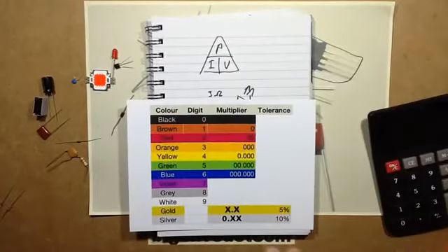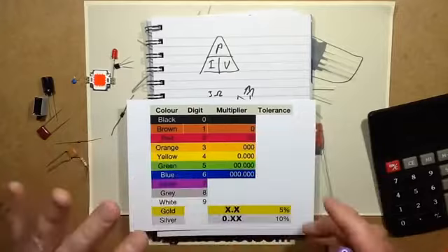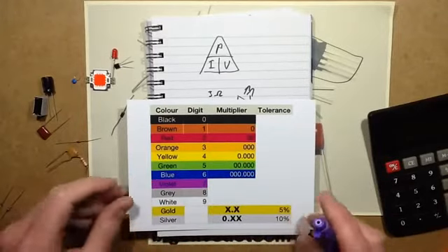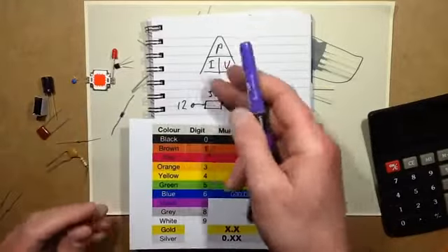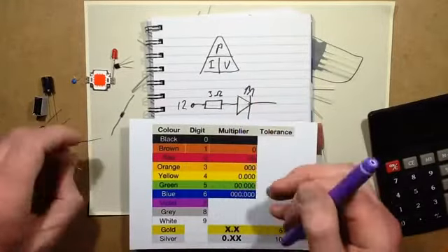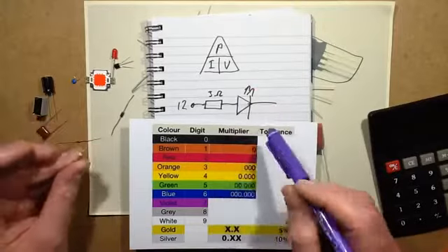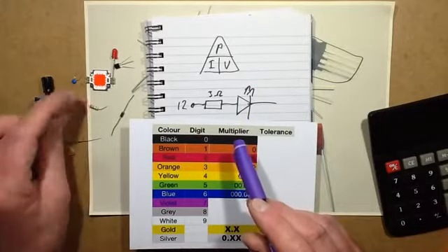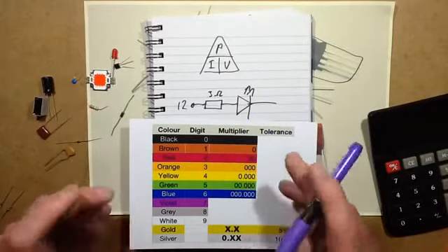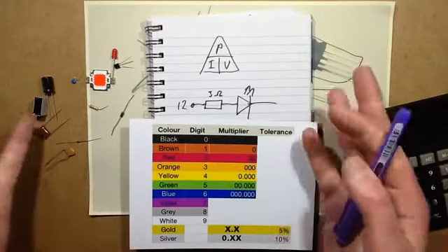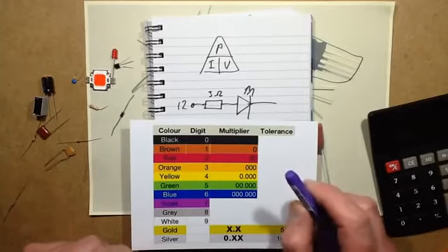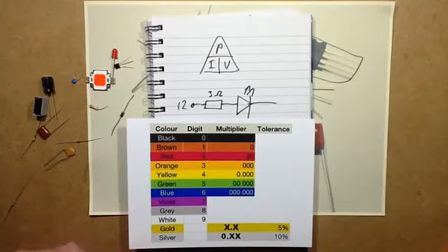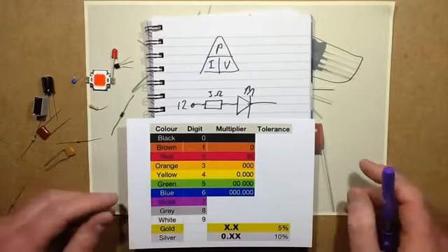That's just a summary. I'm not going to go into too much detail because it would get boring very, very quickly. But this is just the basics of what you need to know, how to work out the power rating of a resistor if you're driving quite a heavy load with it. In most instances, a standard quarter-watt resistor is fine, and how to choose the resistance value to limit current to whatever you want through LEDs and things like that. So fundamentally, that's it. Hopefully that's helped, and I've not overcomplicated it as I sometimes do.